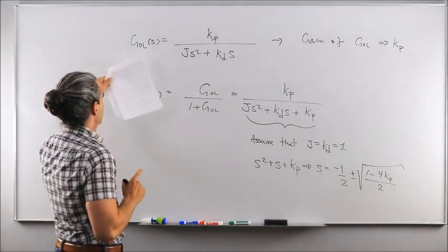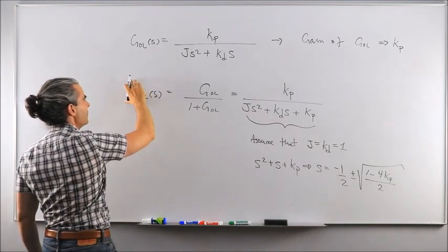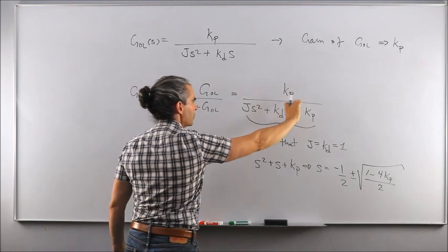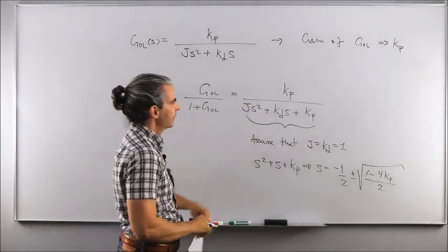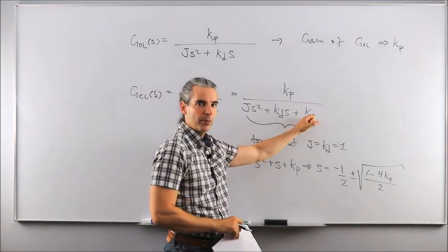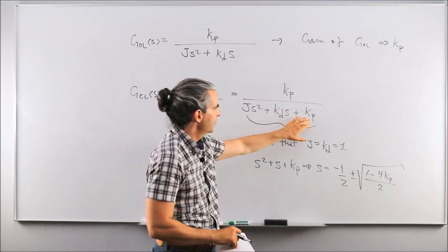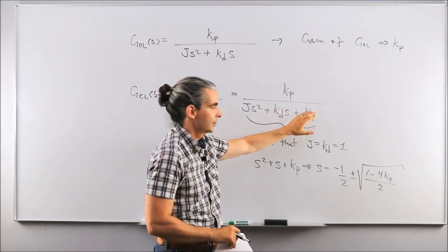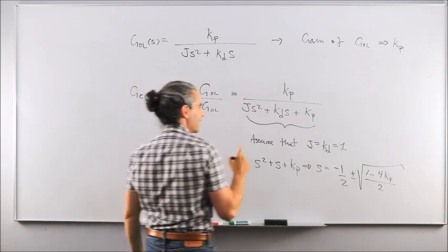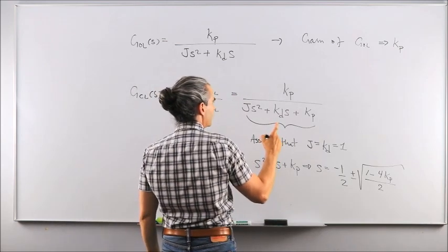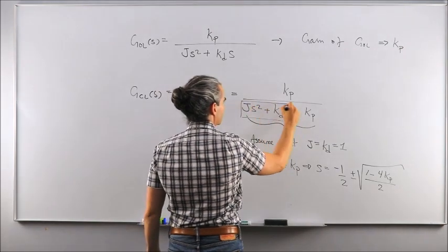And how does that relate to this? Well, that is because if we have a map of the closed loop poles in a complex plane, and if we were to set Kp equal to 0, because remember, the root locus is a map of the closed loop poles whenever Kp ranges from 0 to infinity, whenever Kp is exactly equal to 0, you get this characteristic equation.